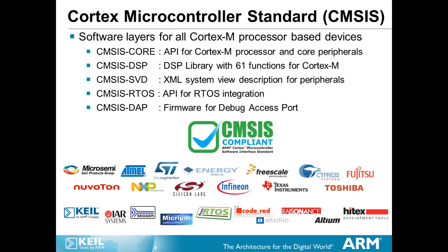To simplify working with Cortex-M-based microcontrollers, ARM has created the Cortex Microcontroller Software Interface Standard, CMSIS. It provides a common software layer for various tasks, from device setup and configuration over real-time OS definition to debug access. Most interesting for this webinar is the CMSIS DSP library, which contains more than 60 operations commonly used in digital signal processing. This library is optimized for the Cortex-M architecture and makes full use of the core functionality.